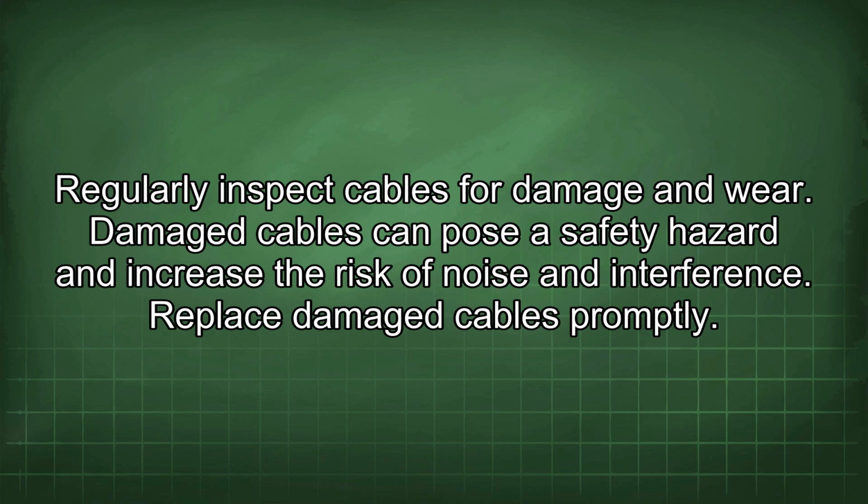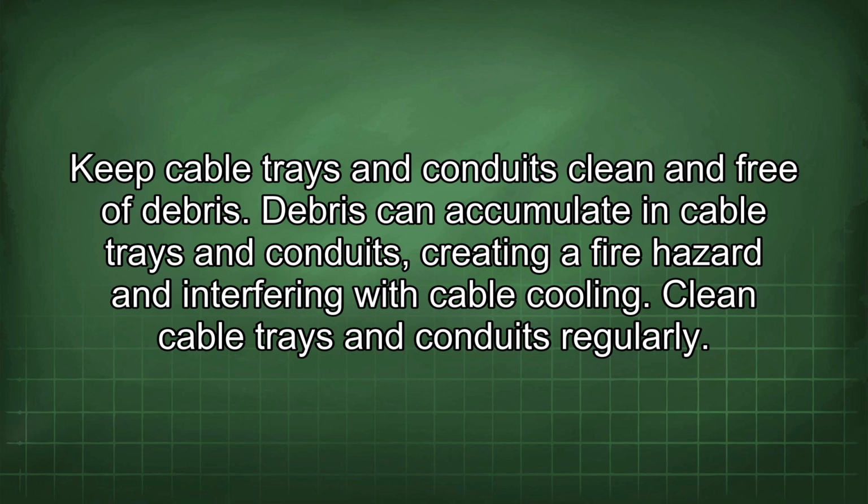Regularly inspect cables for damage and wear. Damaged cables can pose a safety hazard and increase the risk of noise and interference. Replace damaged cables promptly. Keep cable trays and conduits clean and free of debris. Debris can accumulate in cable trays and conduits, creating a fire hazard and interfering with cable cooling.